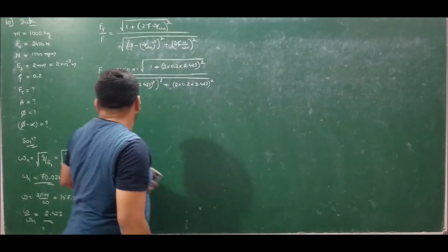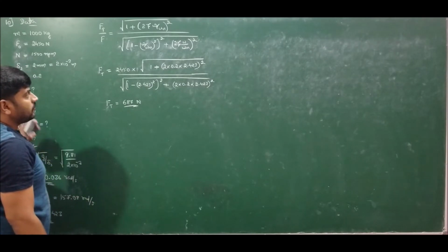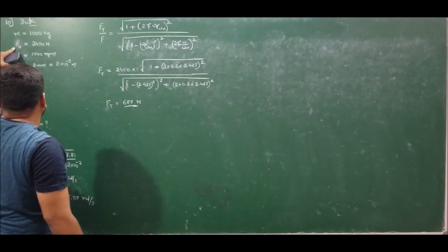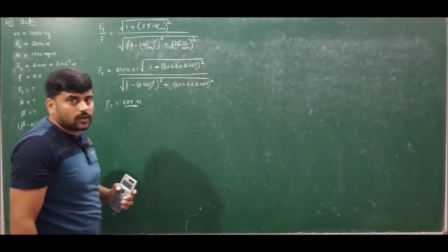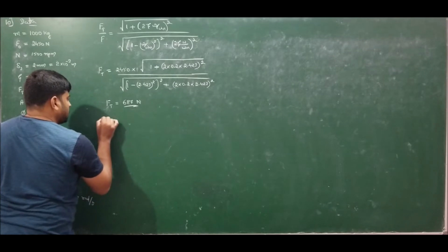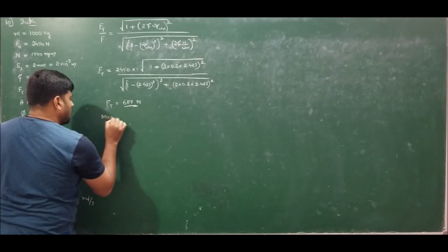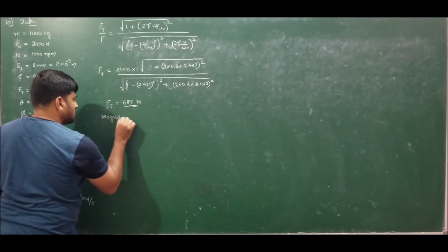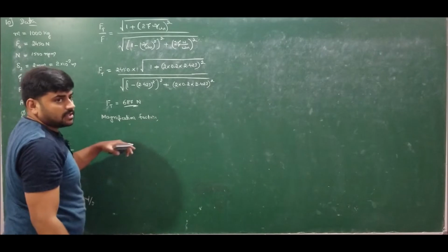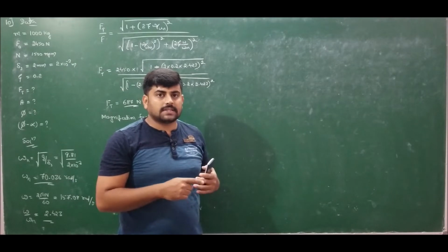Now moving ahead to the amplitude of vibration. To find the amplitude of vibration, we don't know the amplitude of excitation, but we know the force. Force is known for us, so I can use the general equation for amplitude ratio, that is the magnification factor. Recollecting the magnification factor, because it is a general expression using which we have derived expressions for reciprocating and rotating unbalance, support motion, as well as force transmissibility.